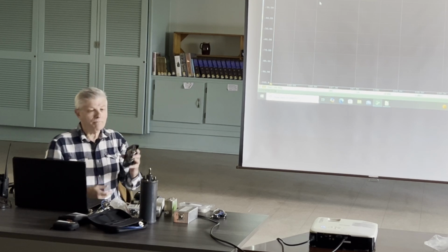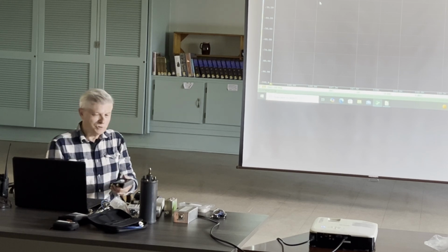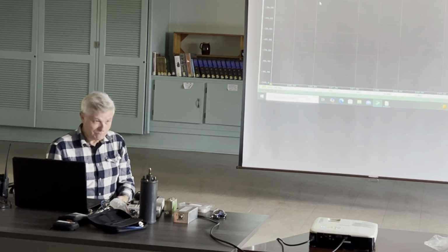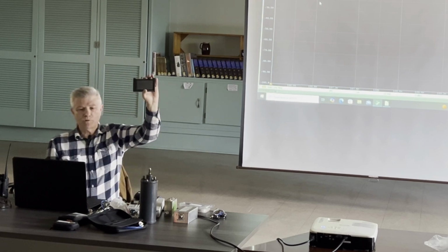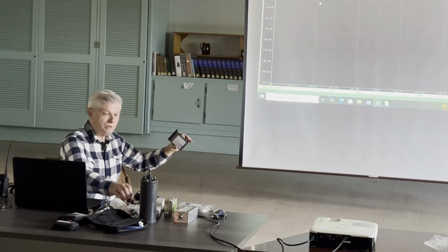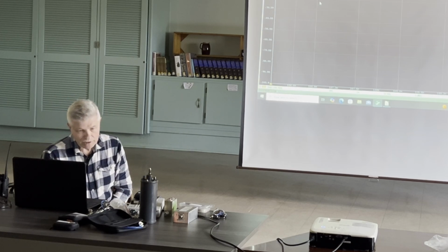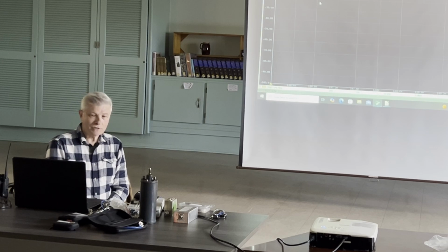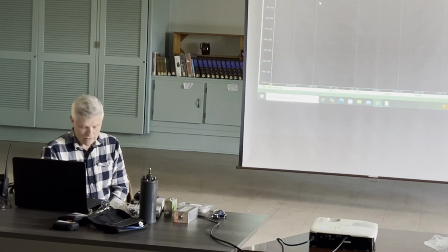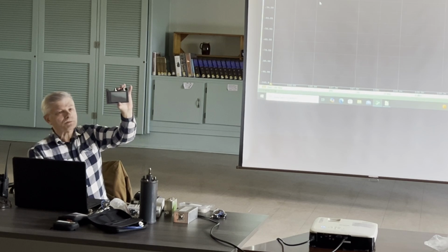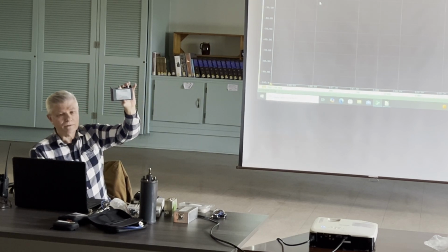And you know what? For 125 bucks, you get a lot of stuff. I got a little carrying case for it, the two cables, a calibration kit, which is probably okay. Here's really the difference between one of these and one of these: dynamic range. You notice that this instrument has at least 100 dB dynamic range. That means you can measure a signal down that far, minus 100. These, not so much. They're probably good for maybe 60 to 70 dB.